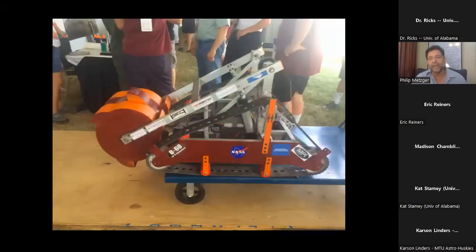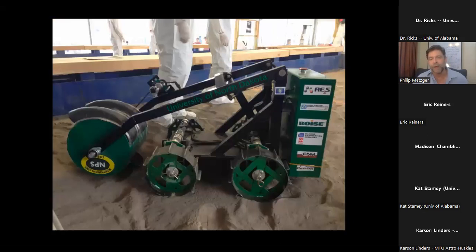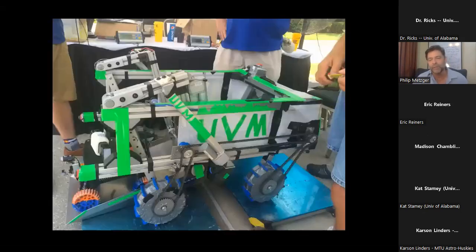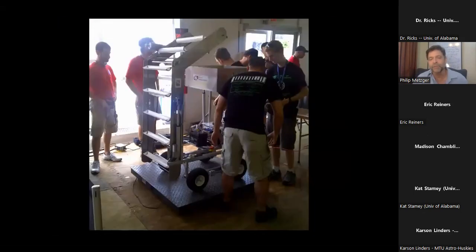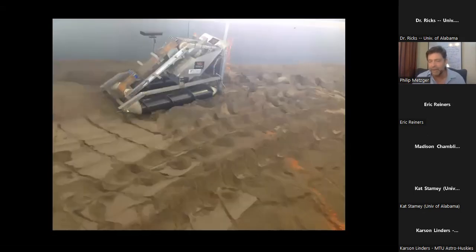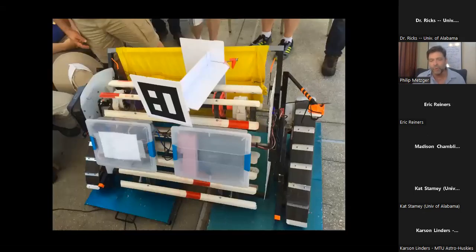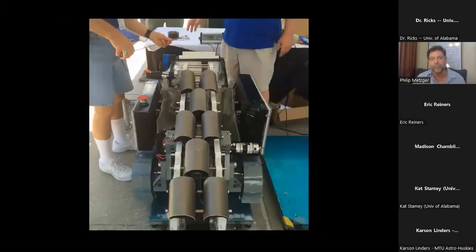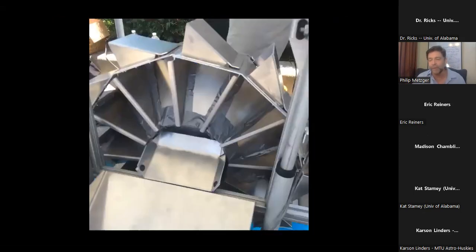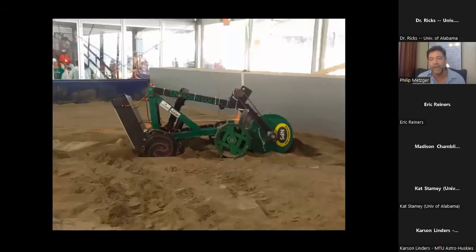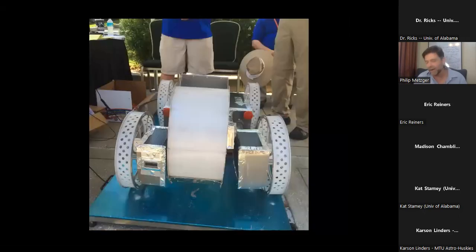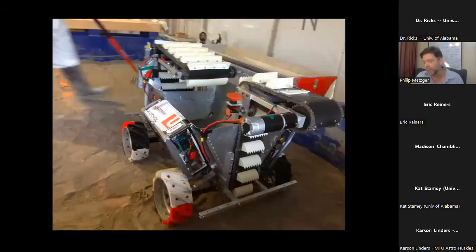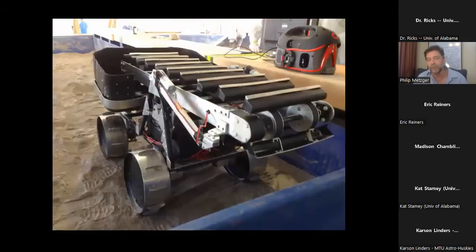So an initiating event could be anything. If you're driving along and one of the wheels bounces on a rock, that little jolt could cause your other wheels to slip a little bit. And that little bit of slip could shear the soil, which loosens the soil and makes the soil weaker. So then the wheel slips even more and it runs away in a self-reinforcing feedback, so it goes out of control, and you end up with a wheel that completely loses traction.